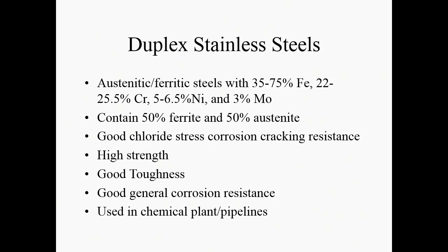And if you're into renewable energy and you've got a solar water heater and you go and buy a water tank, you won't have a copper tank because these tend to operate at a higher temperature, a higher pressure. You'll have a duplex stainless steel water tank in your house. So, you know, there are quite a lot of common applications of this type of material.